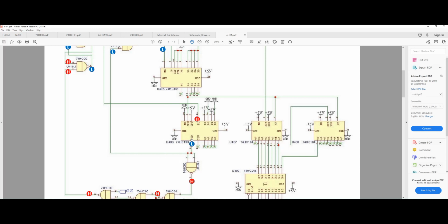And also, if you look at the TCD line, which is the output of this chip, well, the outputs are from Q0 to Q3, but this chip, again, as I said, has two other outputs, which are the TCU and TCD.